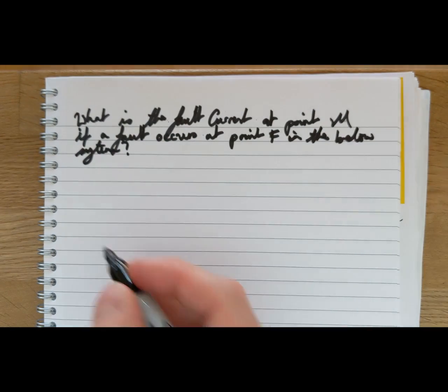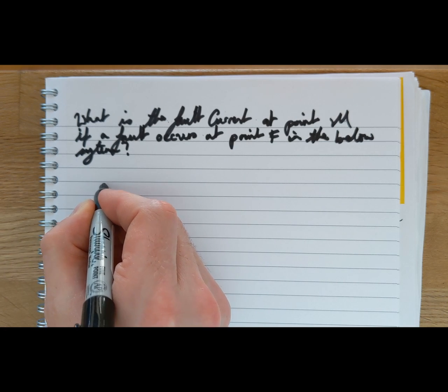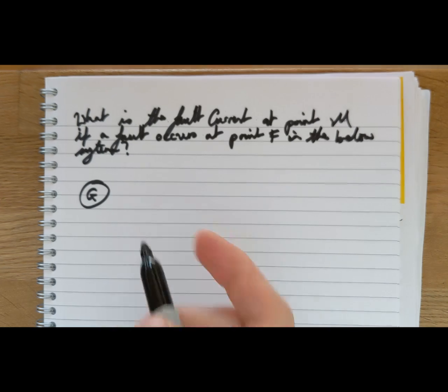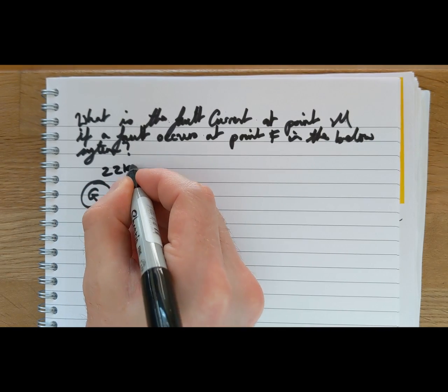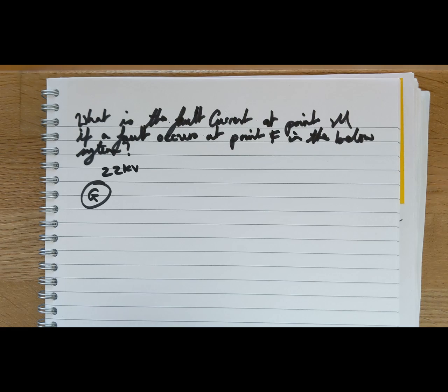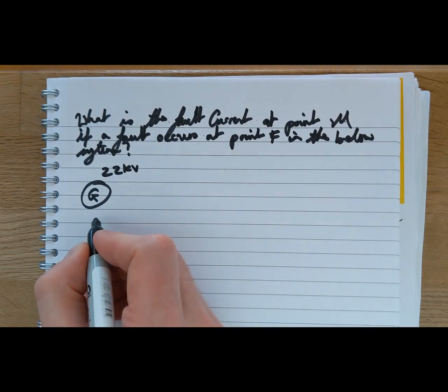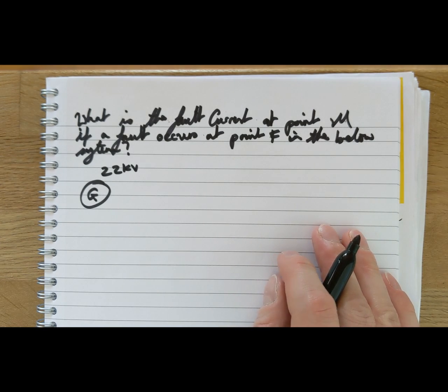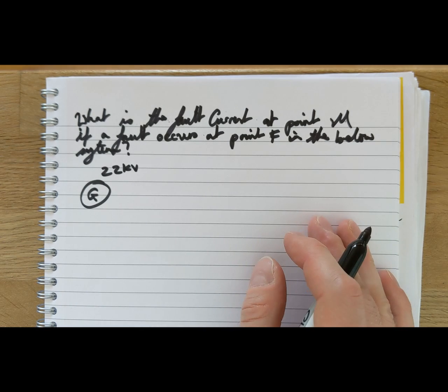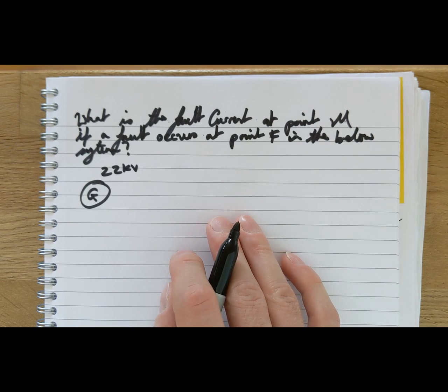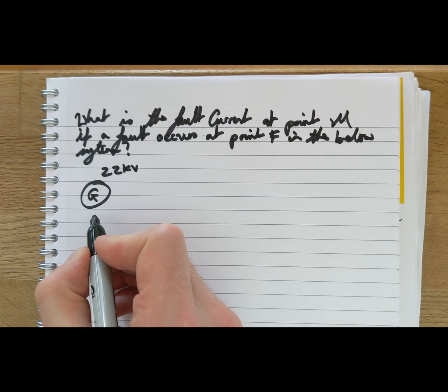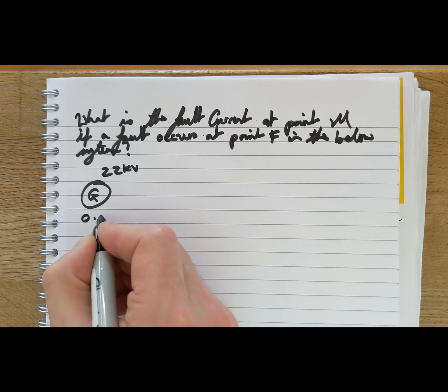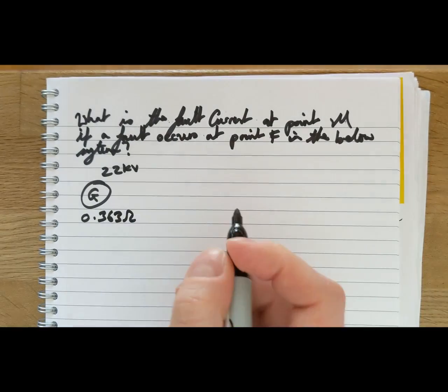And we'll quickly draw the system. So we're going to have a basic generator. It's going to be operating at nominal voltage, and the nominal voltage will be 22 kV. It's going to have an internal reactance, and all resistances will be neglected, and also to make things simpler and quicker, all transformers will have an impedance of 0. But the generator will have an internal reactance of, let's say, 0.363 ohms.